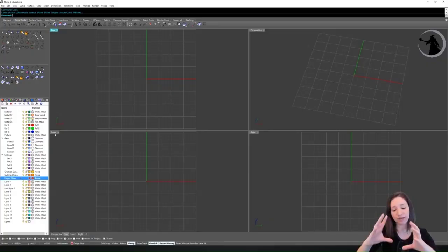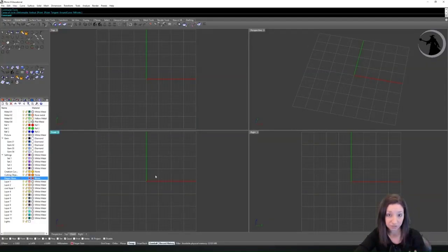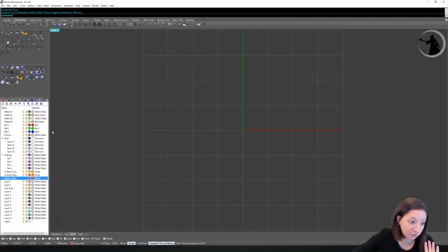If you're imagining a ring, like the through finger view, I'm going to recommend that you always make that your front view. This is how I model things. It makes rendering easier. It makes when you're going to send it to the 3D printer easier. And also it will help you start thinking about CAD in 3 dimensions as opposed to just 2 dimensions. So I'm going to recommend that whenever you're going to draw your circle that's going to represent your finger hole, that you draw it in the front view.